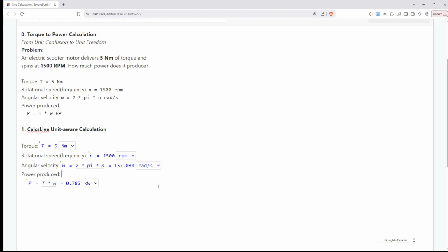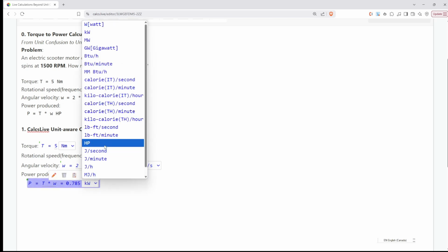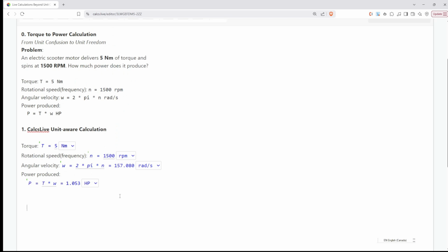And that 0.785 kilowatts for the scooter motor example, that translates nicely, doesn't it? It does. As the sources mentioned, 0.785 kilowatts is actually pretty close to 1 horsepower. Just slightly over, technically, but roughly one. So that little motor twisting with 5 N·m at 1500 RPM, it's giving out about 1 horsepower. Yeah. It kind of gives you a feel for it, connects the calculation back to something maybe more intuitive, that historical measure. That's pretty neat, puts it in perspective.